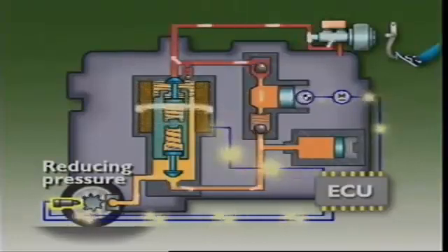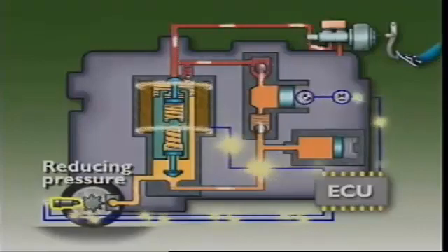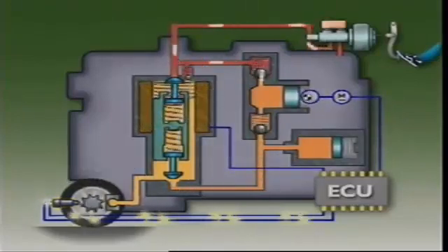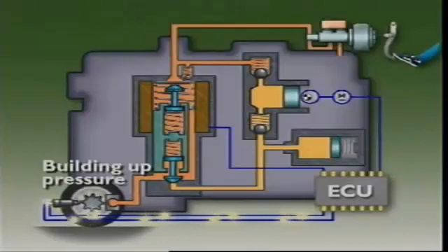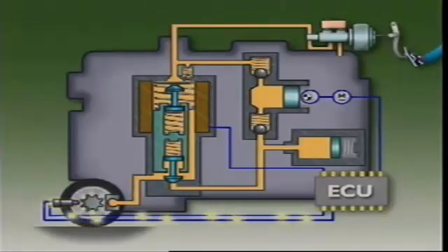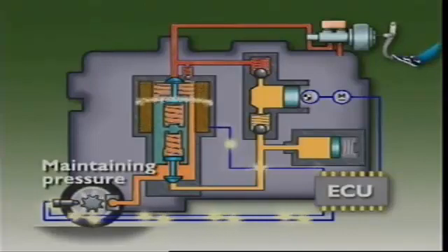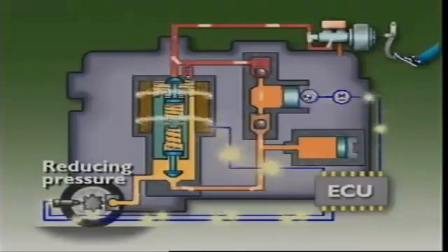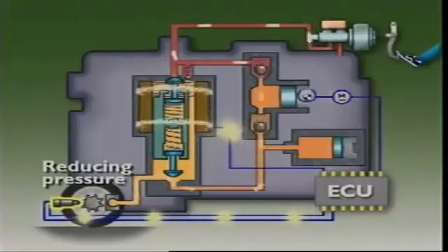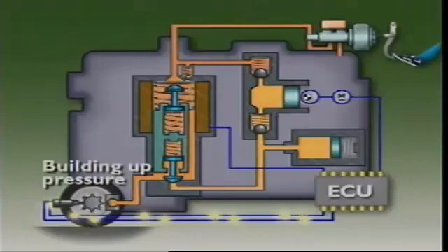If the wheel sensors indicate that lowering the brake pressure is letting the wheel accelerate again, the ECU stops sending current to the hydraulic unit and de-energizes the solenoid valve. This lets the pressure increase so that the wheel is again decelerated. This cycle repeats itself about 4 to 6 times per second. It is normal in an ABS for the valves in the hydraulic control unit to keep changing position as they change the brake pressure that's being applied. These changes in position may cause rapid pulsations to be felt through the brake pedal.